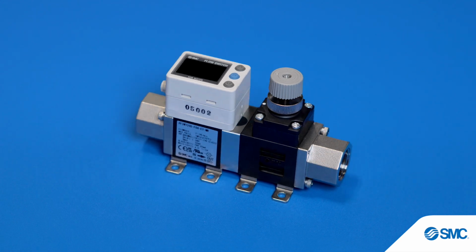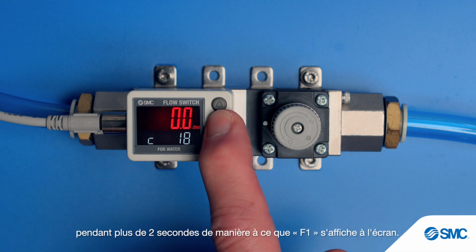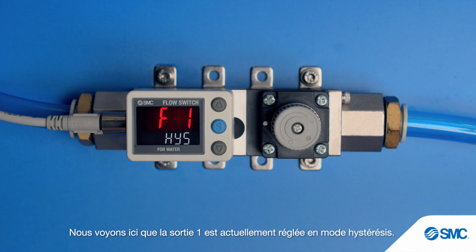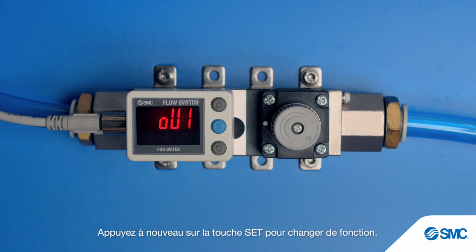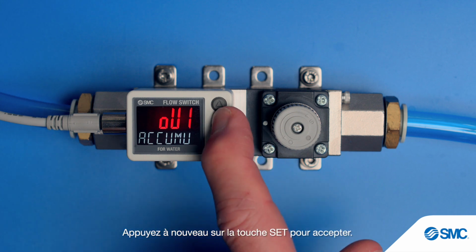Let's start. To set switch output 1 to accumulated rather than instantaneous flow, first press and hold the set button for more than 2 seconds so that F1 is displayed. Here we see output 1 is currently set for hysteresis mode. Press the set button again to allow a change of function. Press the up or down button to select accumulated output. Press the set button again to accept.